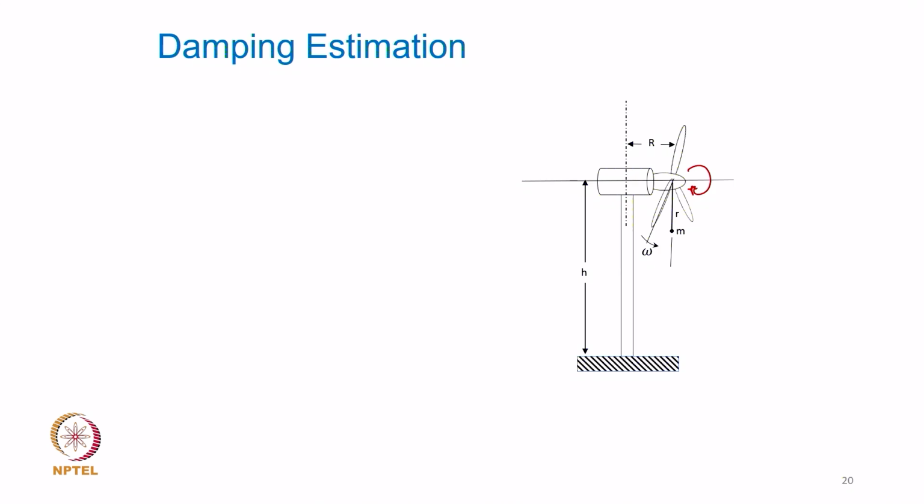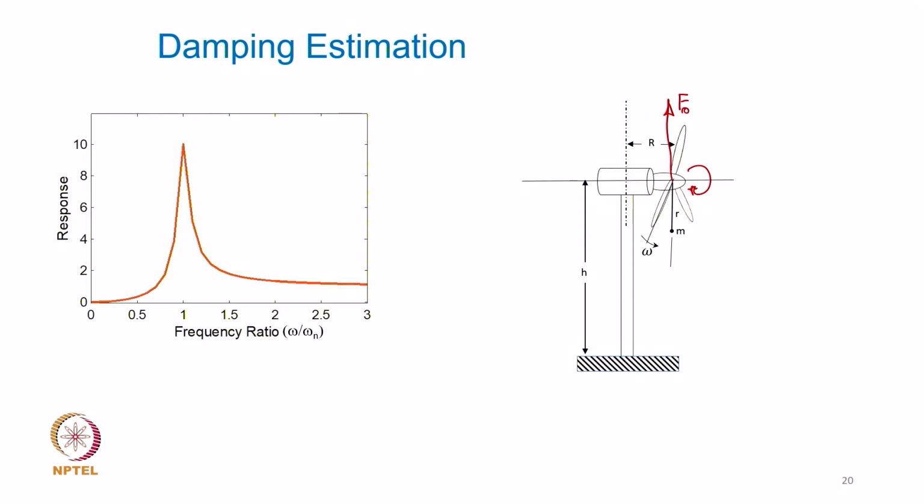These blades will inherently have some kind of unbalance, and that unbalance will create an excitation force which is going to harmonically vary in a rotation, and that is how it is going to excite the system in a forced vibration way. So, if I start rotating this shaft at different speeds, I know that as the speed increases, the amplitude will keep on growing. As it nears the resonance or undamped natural frequency of the system, this will peak and then fall and then go flat from there, right.